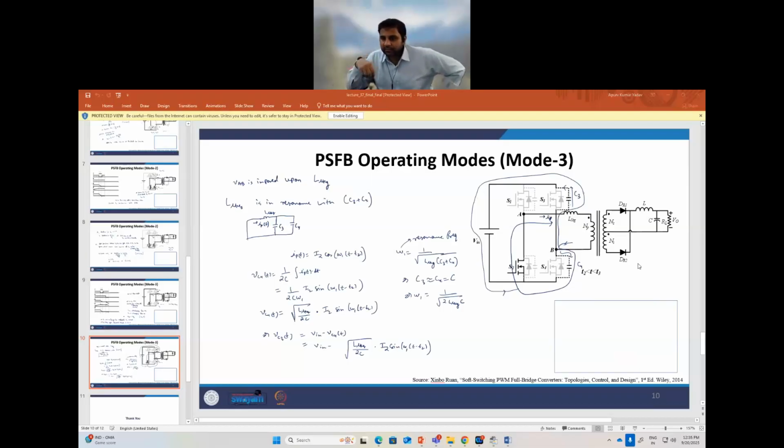Also I suggest from my personal experience, try to use either SiC or gallium nitride devices, because IGBTs are basically rated for higher voltages, so their output capacitances are enormously higher. So you will not get the sharp transition of the devices.